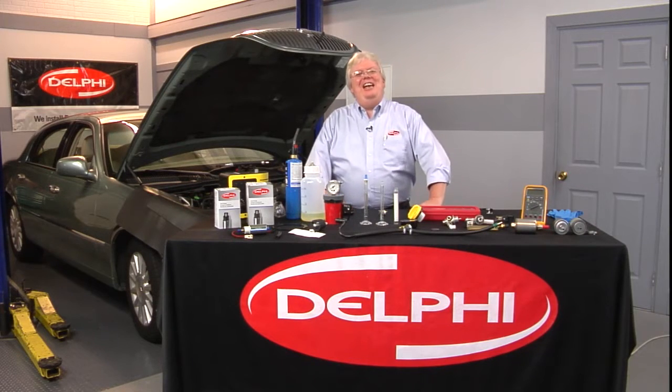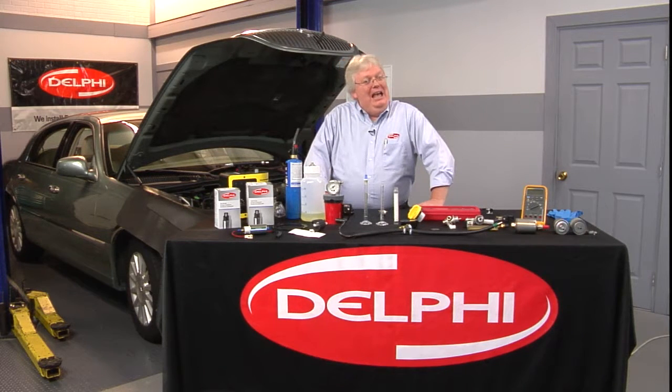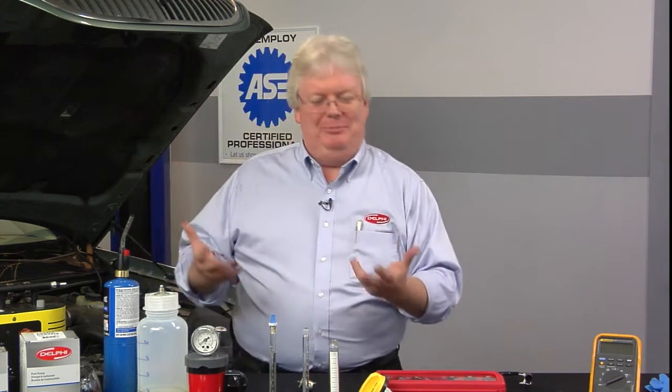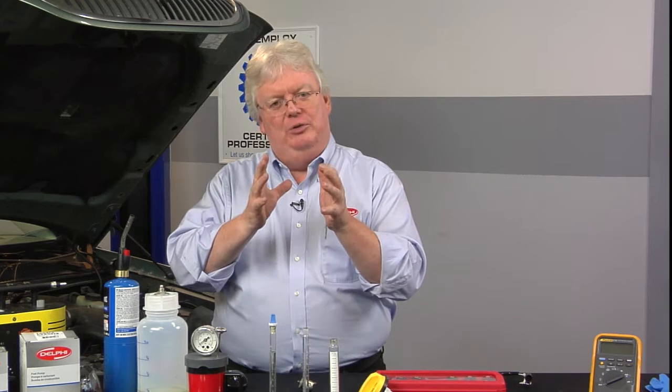Here's a question. What is a PID? I'm glad somebody asked that question. PIDs, TIDs, SIDs, MIDs, that's an acronym. And boy, we are just alphabet soup with acronyms in this business, aren't we? PID stands for Parameter ID. It's short for data PID. You know what data is? That's RPMs, mass airflow, MAP, coolant temp sensor, and so forth. So a PID is basically what you see on your scan tool for live data.